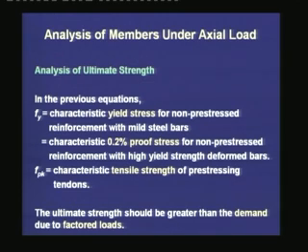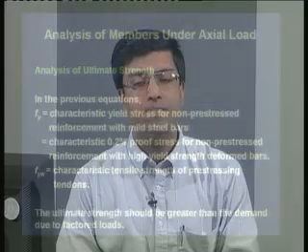For transfer and service loads, we calculated the stresses and compared the stresses with the allowable value, whereas for the ultimate loads, we first computed the ultimate strength and then we compared the ultimate strength with the demand under the ultimate loads or the factored loads.